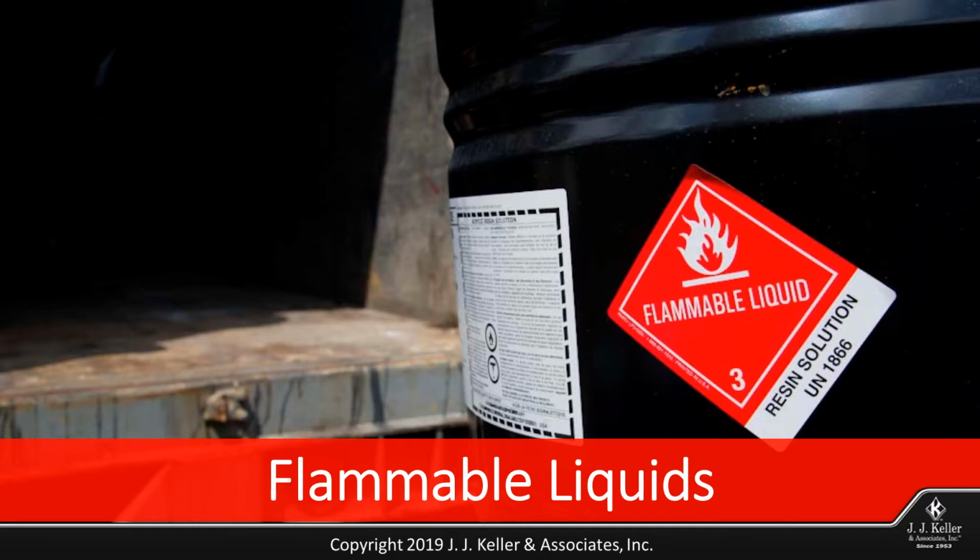When a flammable is spilled, vapors begin to form immediately. The vapors are the fire hazard rather than the liquid. They continue to build until the liquid is removed, requiring prompt cleanup operations. When using a flammable liquid, associates should make sure they have transferred the liquid to an approved container and that it is in a manageable quantity at the workstation.